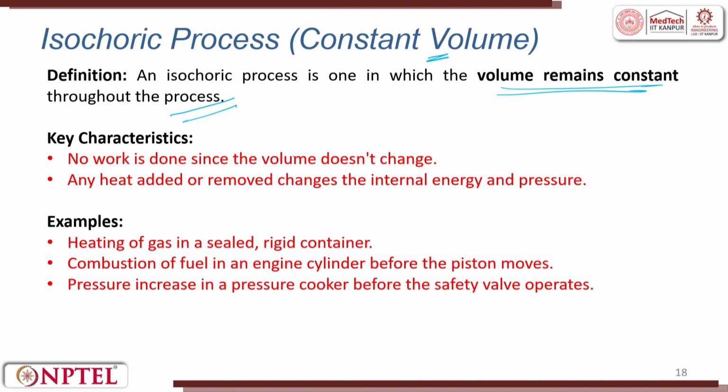So you put a stopper and the volume remains constant. Since the work done is zero, any heat added or removed changes the internal energy and the pressure. Heating of a gas in a sealed rigid container. So you put it like an isolated system, right? Then combustion of fuel in an engine cylinder before the piston moves is also constant volume.